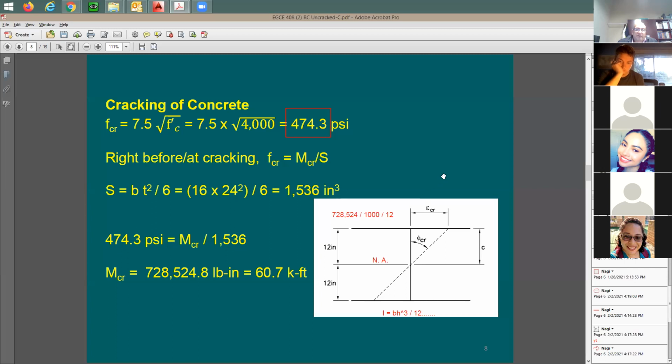And as long as you start to add more loads, what's going to happen? The crack width is going to increase. It's going to get larger and larger. It doesn't mean now the beam is failing or anything. I mean, once you see some cracks at the bottom of the beam, it doesn't mean that the beam is collapsing, right? It's going to collapse at a certain crack width, at a certain given load that we can calculate. We're going to do this for our design.